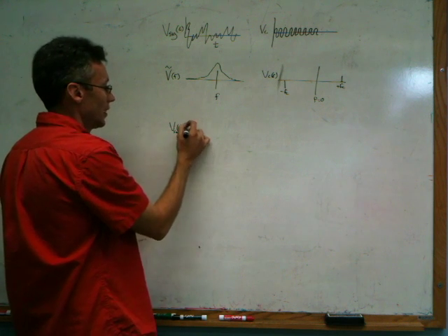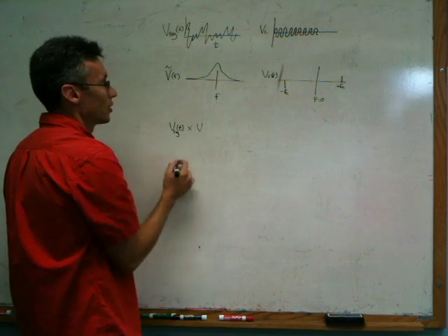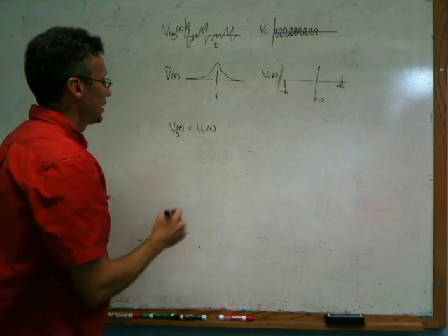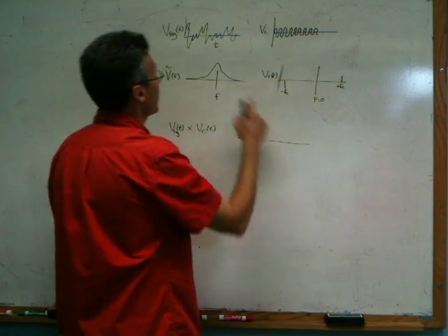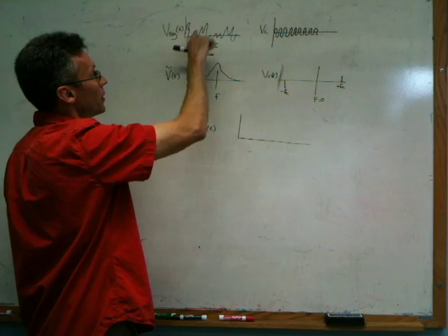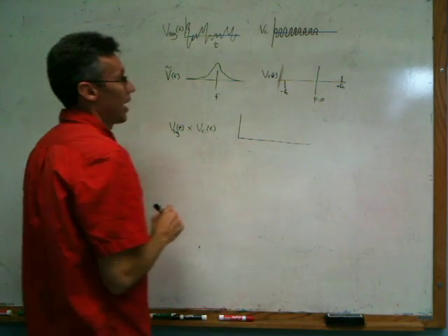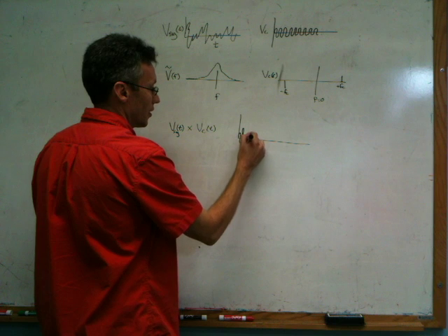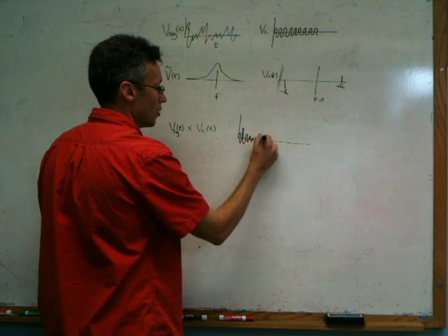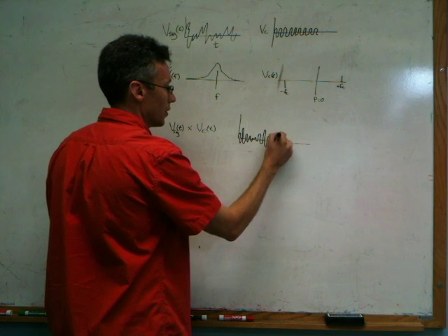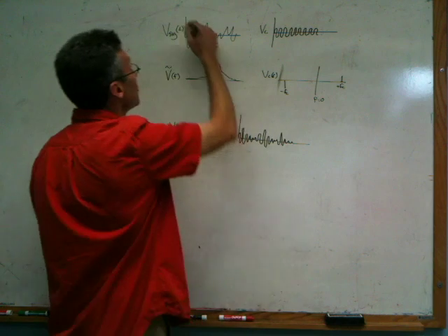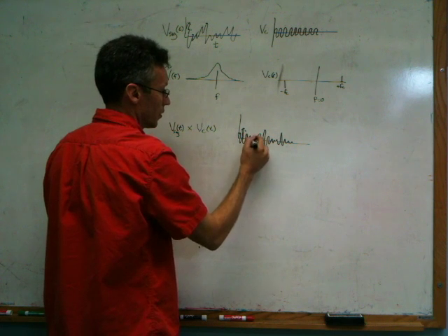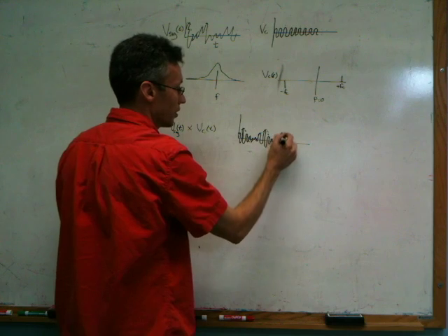So we can take our signal, and in this case, modulation will be multiplication by our carrier wave. And in the time domain, what that's going to look like is our original signal will form an envelope over this higher frequency carrier wave. So we'll still have these sinusoidal oscillations that we had at the carrier frequency, but now their amplitude is going to be modulated by this function here. Right, so this represents amplitude modulation.